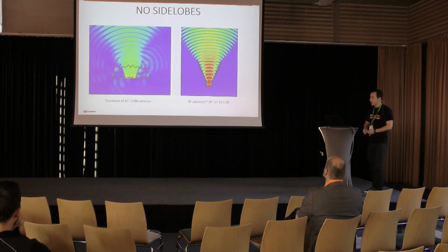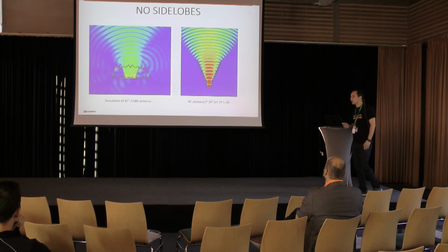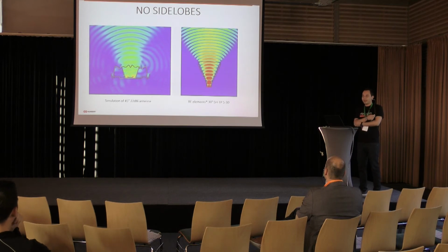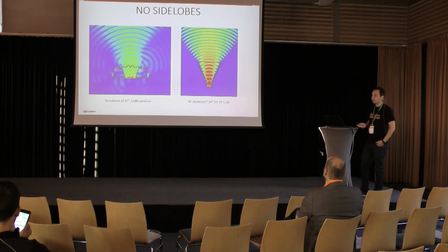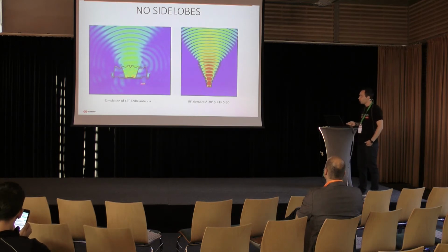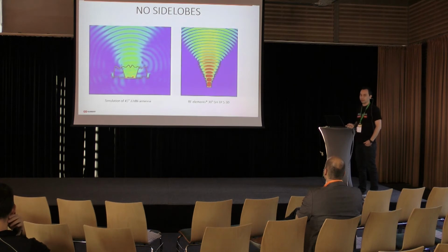This is the simulation of another antenna which has already pre-installed shielding in the back, but not each piece of metal can be called a shielding. For a shielding, it's really important to know how to do that. And as you can check, it eliminated the back lobe of the antenna. It's not so critical right now, but look what happened with the main beam. As you can see, all this main beam is moved to the left side, and for MIMO technology, that's a huge problem.